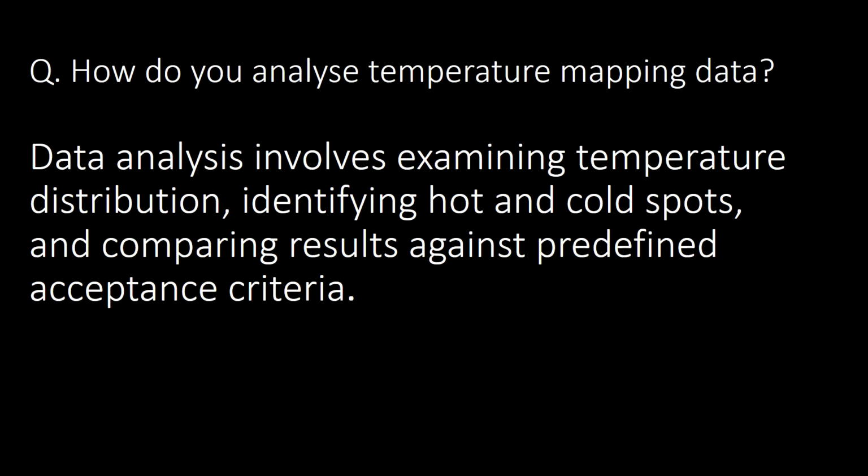How do you analyze temperature mapping data? The answer is, data analysis involves examining temperature distribution, identifying hot and cold spots, and comparing results against predefined acceptance criteria.